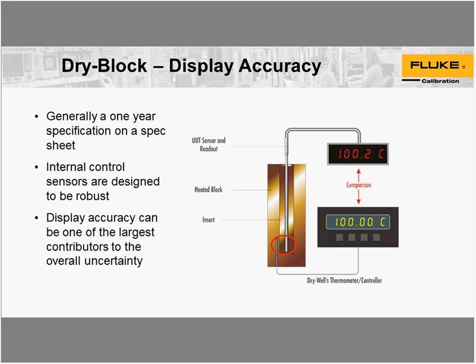It's also recommended that if you're shipping them, you remove all the inserts from the wells before shipping them out. Because if it's down there and bouncing around during shipping, it can cause physical shock to the sensor itself. When you're looking at dry wells, please be wary of the display accuracy, because that's typically one of the larger uncertainties of a dry well.